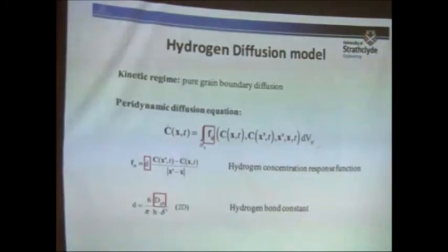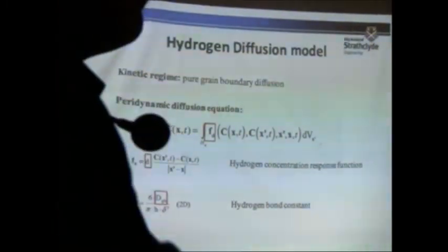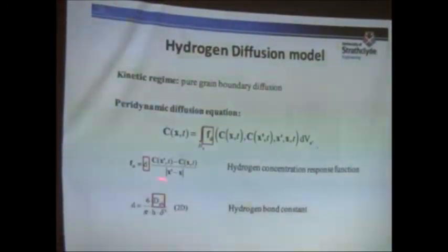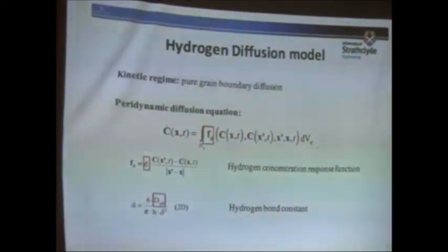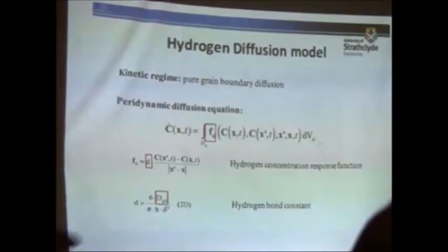So it just depends on the amount of hydrogen. Although peridynamics was originally introduced for structural analysis, now we have peridynamic formulations of other fields. For example, this is the peridynamic form of a diffusion equation, so that you can solve multi-physics analysis in a single peridynamic framework.